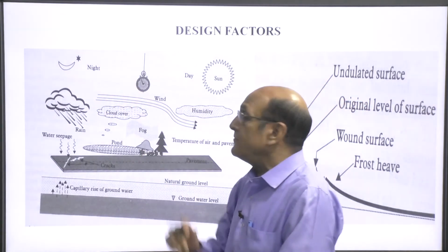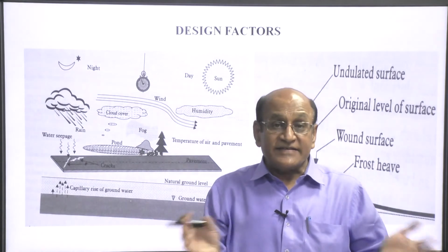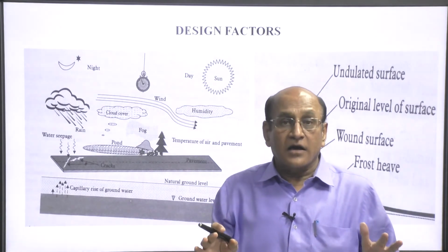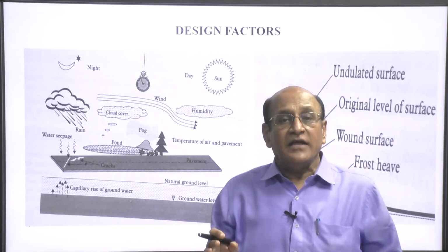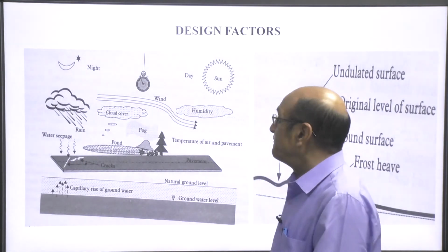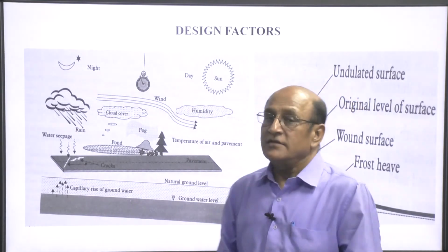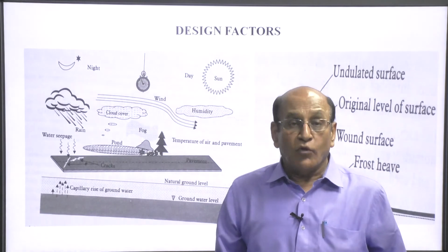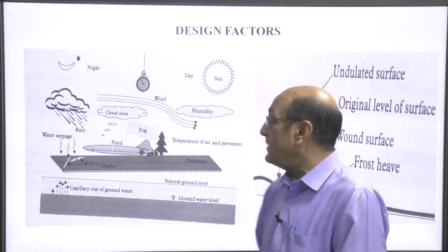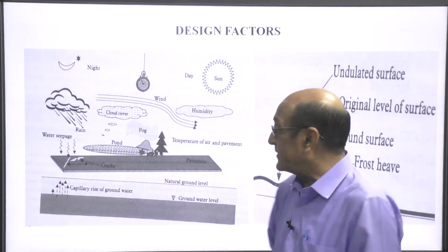This is night time where the temperature stresses provide wide variation. At daytime, the sun will provide higher temperature and produce higher stress in the pavement surface, especially in the rigid pavement.